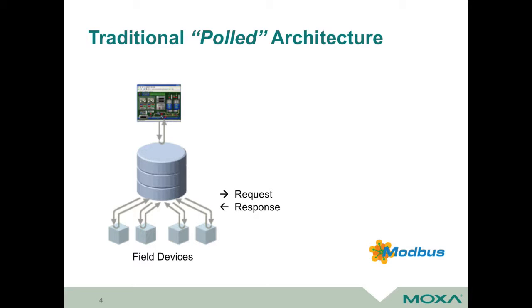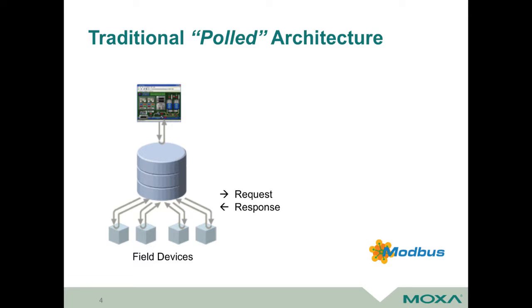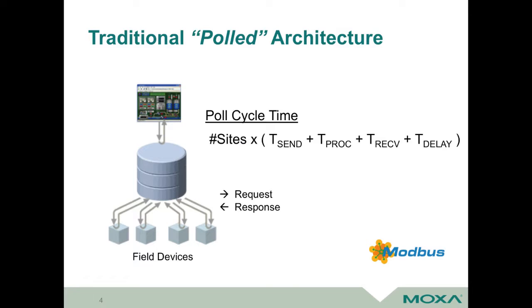When you're using Modbus, you have to ask a question: tell me the value of the tank level, right? That request comes down through the system and gets pushed out to the edge device. Then the edge device replies and it comes back up. So it's kind of chatty, request and response. How are you feeling? Good. How are you feeling? Maybe not so good. Whatever that might be. When you look at this in a little more detail, what you'll find is that you have a polling cycle to do these things, right?